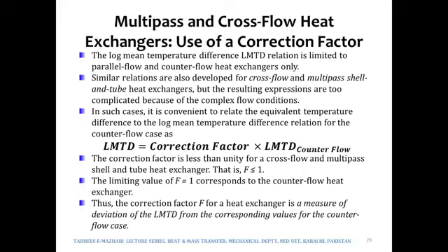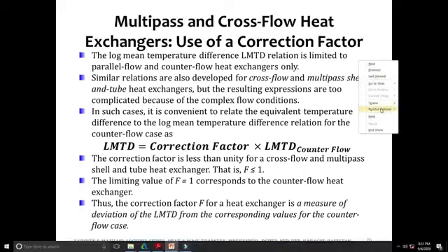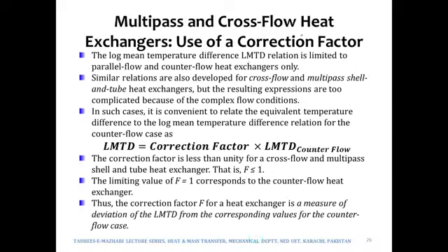So in those cases where it is neither completely parallel nor completely counter flow heat exchanger, we then use a correction factor in finding out the log mean temperature difference.